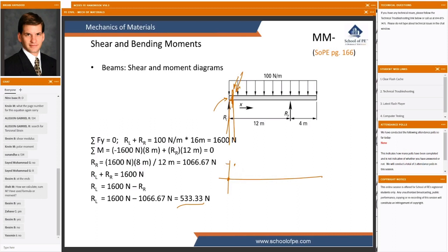Or if we go with the approximation given in our original problem statement, if we pretend that it actually is just a point load, that is, it's supported across a negligible width, then I can say that I really and truly do have 0 shear at the end, and I really and truly also have 533 shear at the end. I've collapsed that support down into an infinite slope, so I do have a value of 0, I do have a value of 533, and I do have every value in between applied at that left-hand edge.